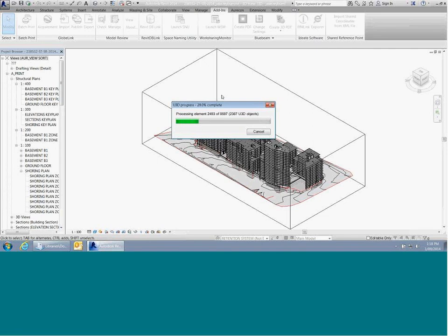No, that still makes sense, doesn't it? Because I've selected in the settings to include properties, I think it was, the tick box. Everything you select has a property and it's exactly the same. It even has an element ID, everything like that. So you could even type that into Navisworks if you had a Navisworks of this model. You could actually go straight to that element from your PDF, if you search the number up.